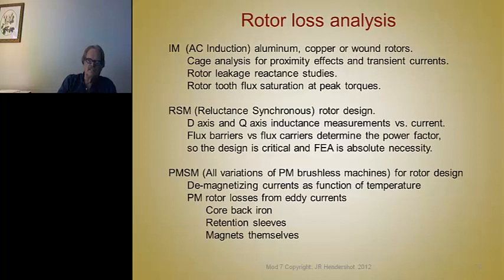The other thing is that neodymium magnets have a very poor thermal characteristic with respect to the B. The flux density varies as, let's see, I believe it's like 0.10 to 0.12% per degree C elevation in temperature, you lose in B.